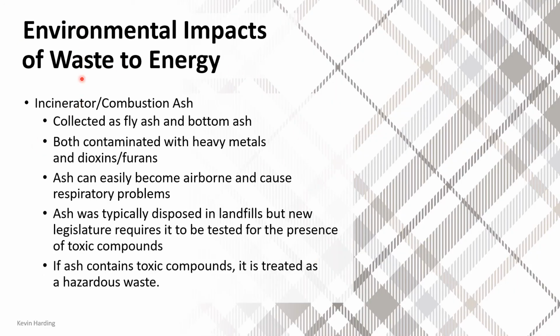I think some of this is repetition now, or it's kind of obvious from what we've been saying, that when we burn this solid waste, it's going to form ash. That ash we can collect as fly ash as well as bottom ash. Both can be contaminated with those heavy metals or with the dioxins and furans. This ash, because it's such a fine particle, can easily become airborne, so that's going to lead to respiratory problems. If it has toxic compounds, it needs to be treated as a hazardous waste.